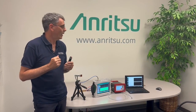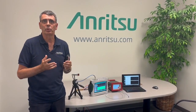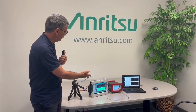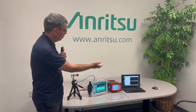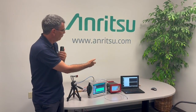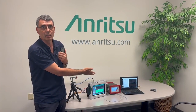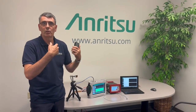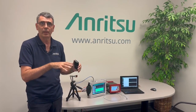Welcome to Anritsu Labs. Here in our test lab today, we're going to give a demonstration of capturing IQ data from a pocket radar, capturing it on the MS-2090A Field Master Pro, pulling that IQ data into our IQ Signal Master applications running on a PC, converting it to a format that we can push into the AnaPico 40 GHz vector signal generator, and then playing that file back. So we're going to show a complete closed-loop system of capturing IQ data and then playing it back.